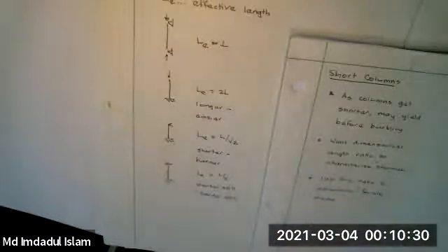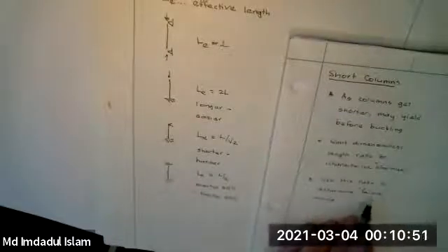Failure in inverted commas. I mean, as I've said, things can buckle and then go back again and not fail. On the other hand, once they start to do that, they're going to start to see big stresses. And if it happens repeatedly, it probably does lead to failure. And likewise, they may not buckle at all, but they may start to yield. And if they see that repeatedly, they will fail. So when we say fail here, we're meaning in the long term. Okay. But as a precursor, when you design, if you see this happening once and you think you're going to have repeated loading, then you want to avoid this, even though one-time loading wouldn't really lead to a failure.